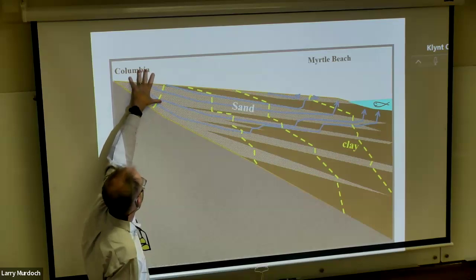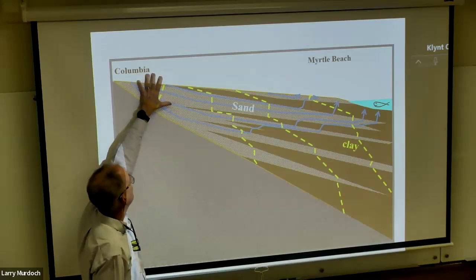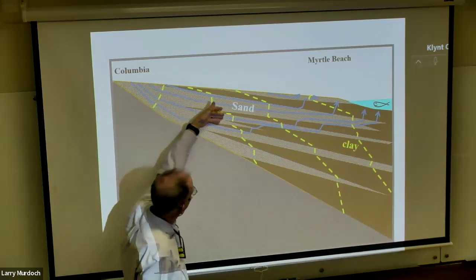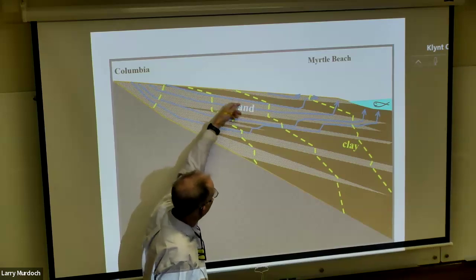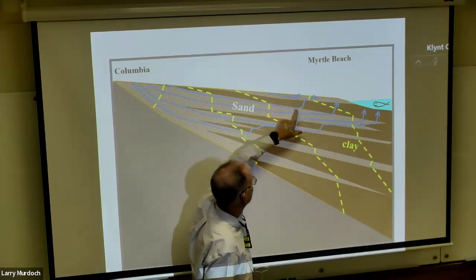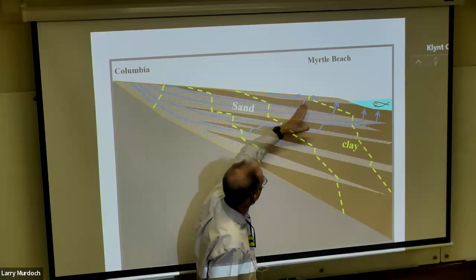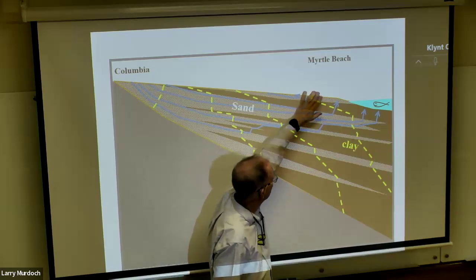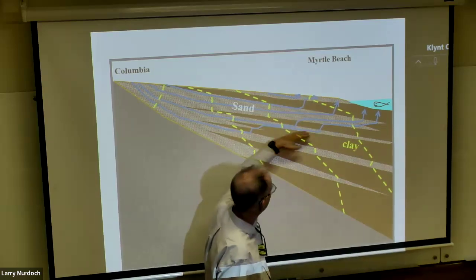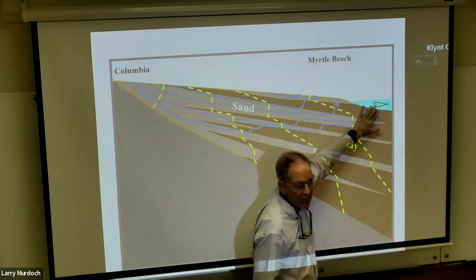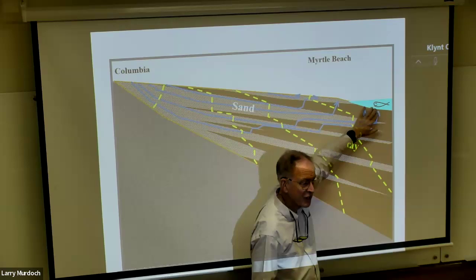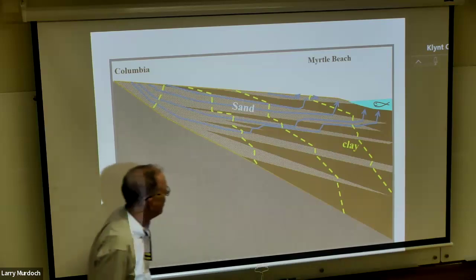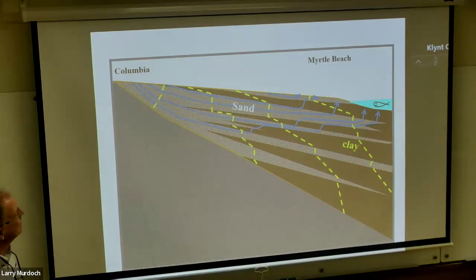The flow is generally kind of a regional recharge system up here, and then flow down through these confined aquifers. And in places, the flow needs to go through the confining unit, so it's coming back up and discharging. In this case, it would discharge to a stream. But here we have flow coming up and then also discharging here to surface water, but in this case, it's fresh water discharging to the ocean. Okay, so that's what the flow system looks like.